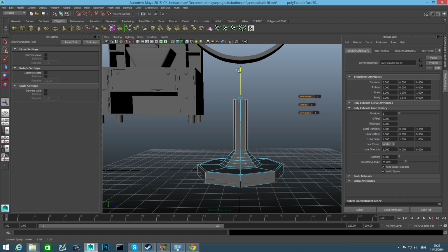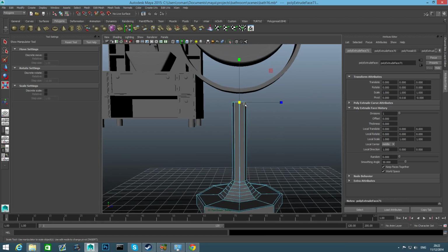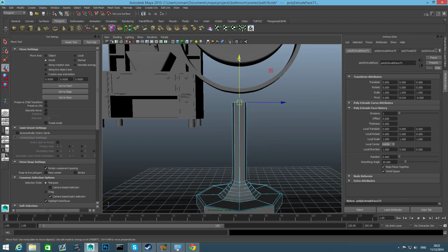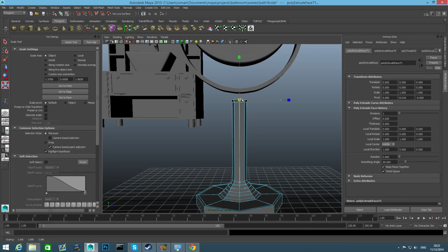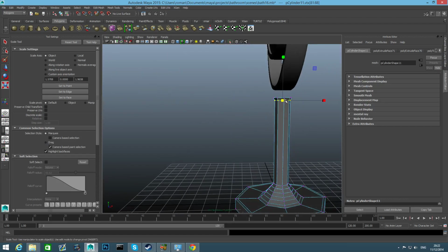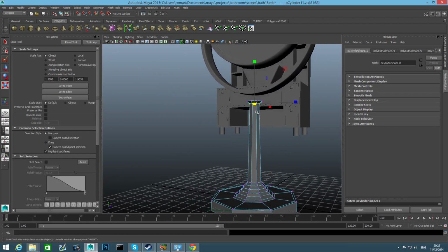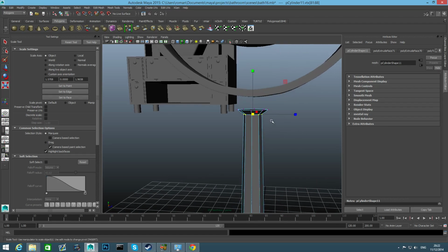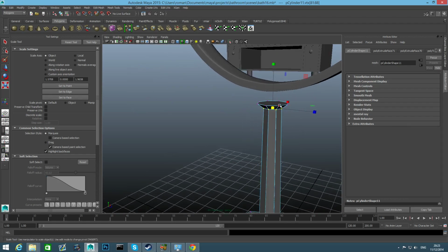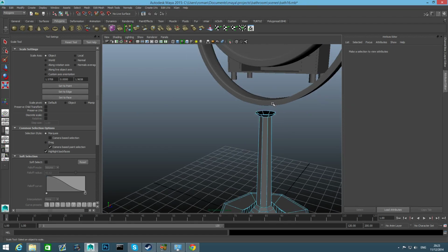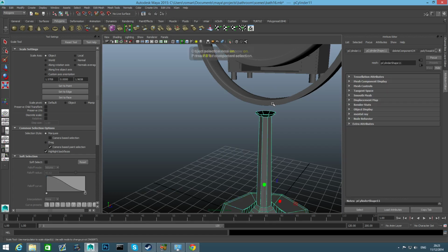Extrude it, and here we'll do the same thing we've done earlier. So simply bring this that way, maybe pull this, and those I will shrink them a little bit to narrow this and keep this as it is. So right click, choose, press F8, right click, choose face. Let's grab this face. Let's delete it. Press F8 to bring it back to object mode.